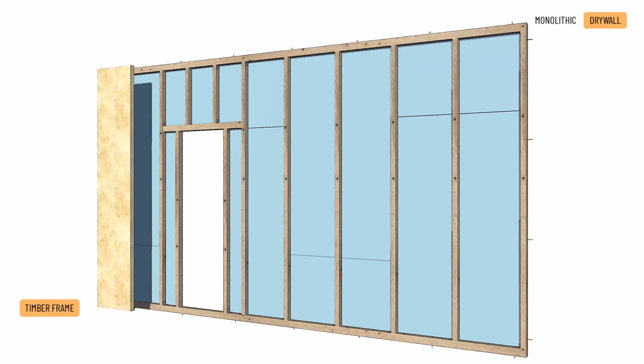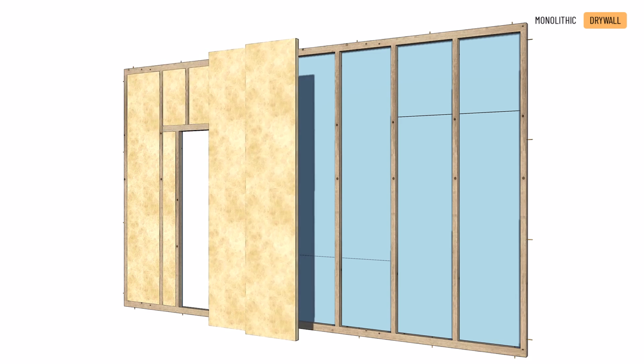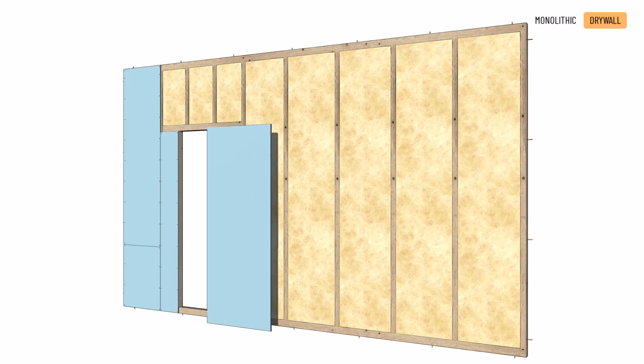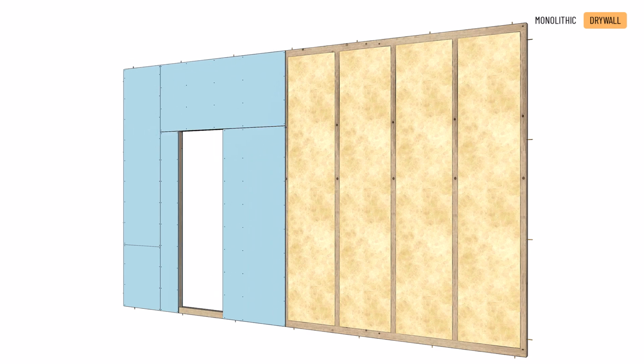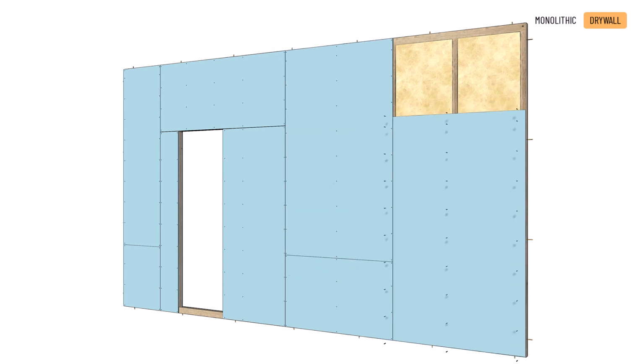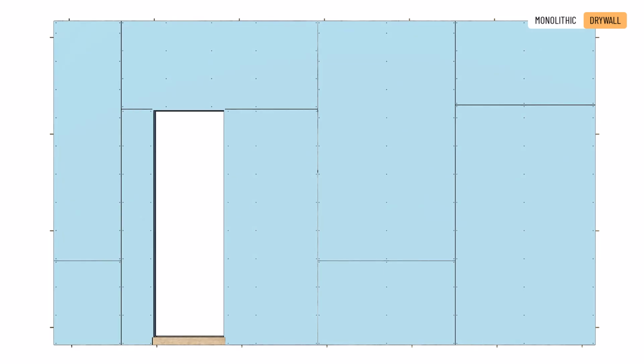Mineral fiber wool, glass wool or rock wool is placed between the studs to provide thermal and acoustic insulation between adjacent rooms. Then, after cutting the individual boards to the required size, screw the gypsum board or plywood onto the stud wall. Putty can be used for the board joints, screw heads and other irregularities to form an even, flat surface to prepare it for painting.